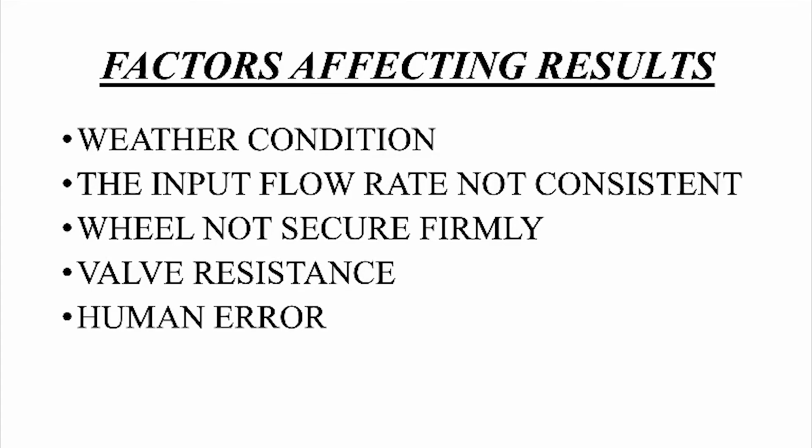Thirdly, the wheel was not secured firmly to the stand. In future constructions, the wheel should be prevented from moving on the x-axis. In our experiment, the wheel would have moved slightly to the left or right. This would decrease the amount of energy being supplied to the wheel and would hence decrease its rotation. In addition, the resistance of the valve was slightly higher than the estimated theoretical value, which would decrease the input into the wheel and hence decrease the output.